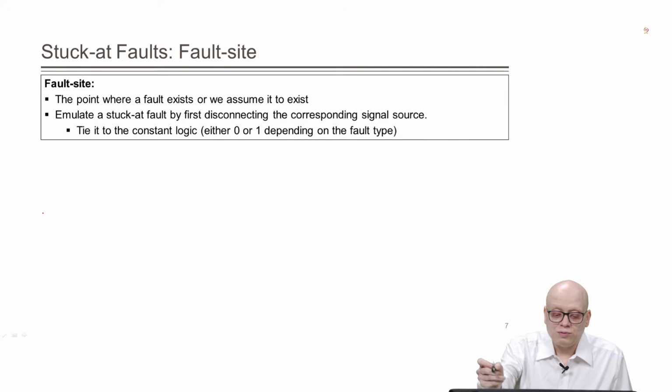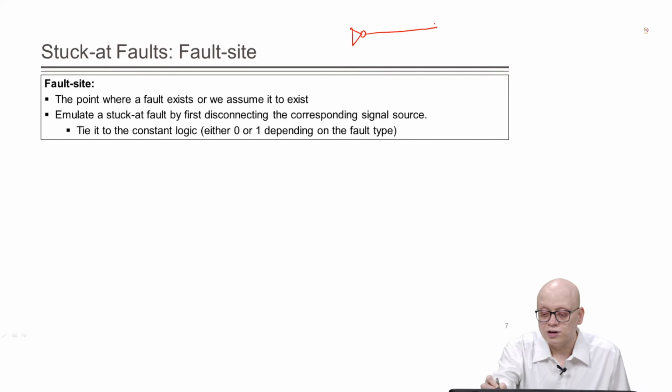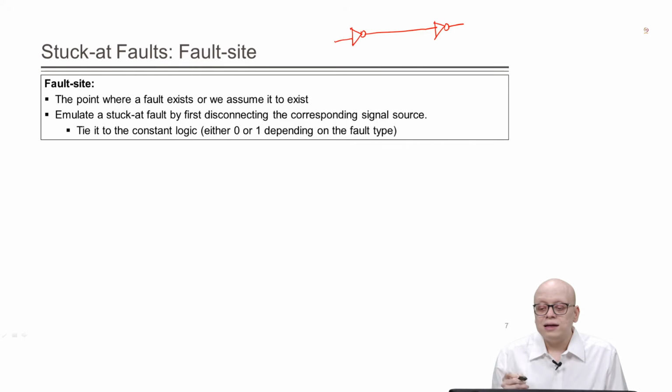Suppose we have a NAND gate driving an inverter I1, which drives another inverter I2. We say that the input of I2 is stuck at 0.